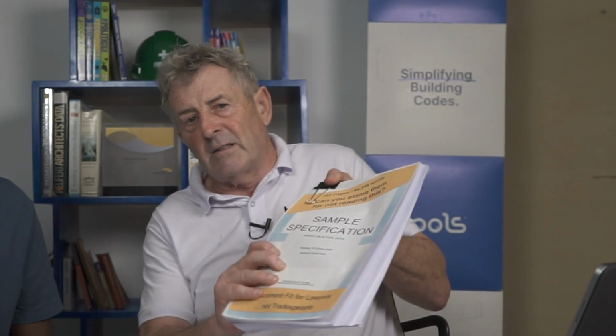And you've said to me before that typically specifications are read for the first time in a building dispute. Yeah. And I don't want building disputes. I don't want the problems to occur. What I want to do is have the information that the specification says it's meant to contain in front of humble me. When I'm doing a fire stop detail, I make sure it's the correct depth, and the gap between the penetration and the service pipe is compliant. Yep.